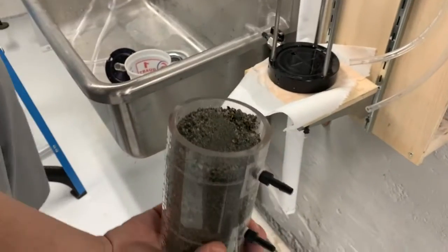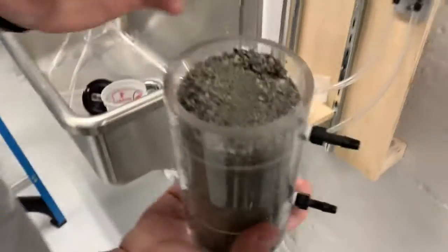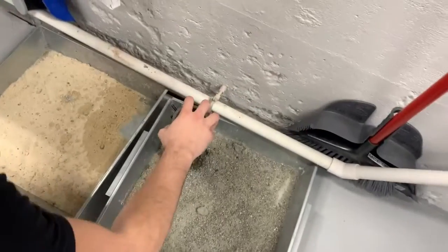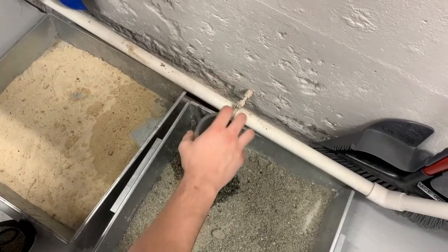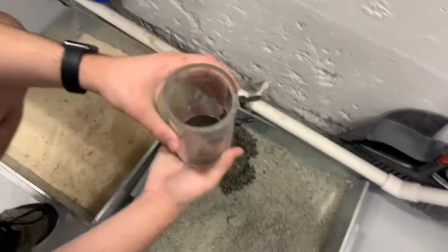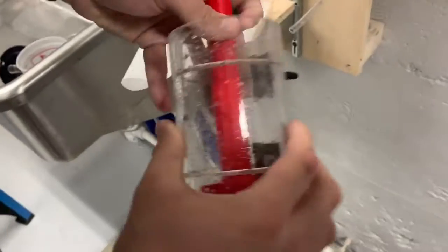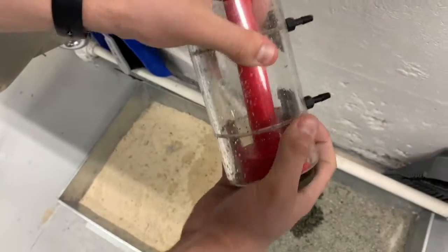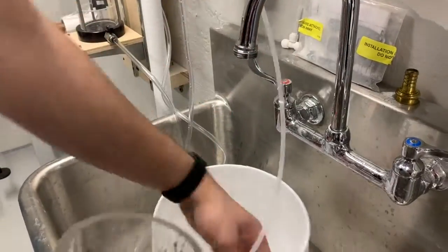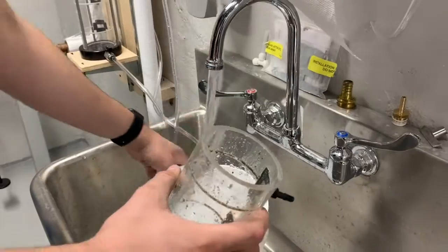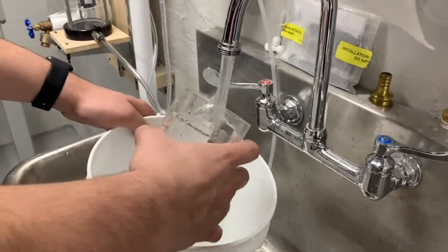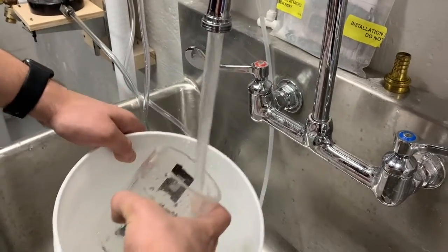You could then tip the cylinder upside down and dump the rest of the sand out in the drying pan. Best sandcastle wins. Then we can use a 3D printed part to remove the bottom porous stone. Finally, you're going to want to rinse out the rest of the material from the cylinder. Once the cylinder is clean, dry it, and then you can prepare for your next test run.